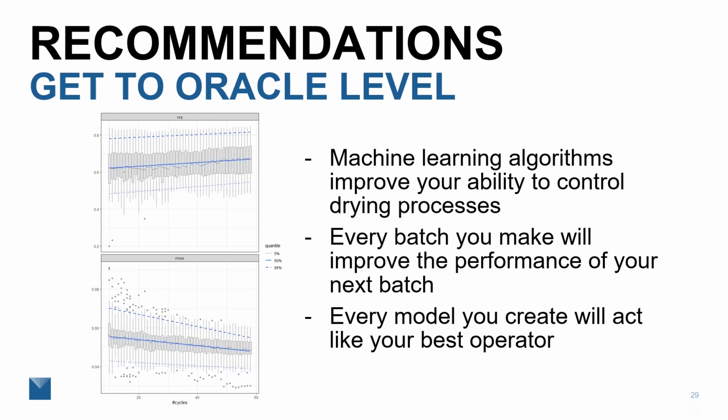And now the system alerts operators when drying processes should be stopped to achieve target moistures. This has reduced the standard deviation of batch moisture content by 55% after 3 months. Please don't get hung up on the fact that this customer's drying process control variable is dwell time. The system works whether your control parameter is dwell time, belt speed, oven temperature, steam settings, or anything else.